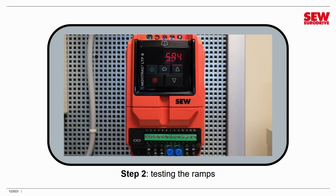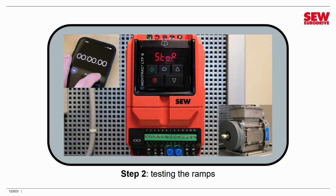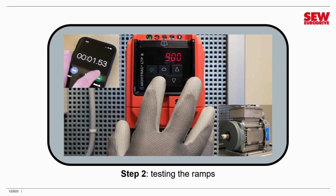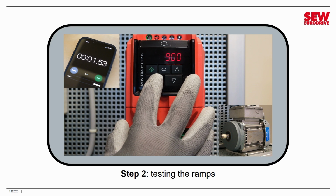I'm going to hit the stop button, bring my VFD to a halt, and I'm going to get out my smartphone and bring up a stopwatch app. What I'm going to do now is start my stopwatch simultaneously with my VFD, so I'm going to press start on both of them at the same time. Here we go. All right, and you can see that took about 1 second to get up to 900 RPM.